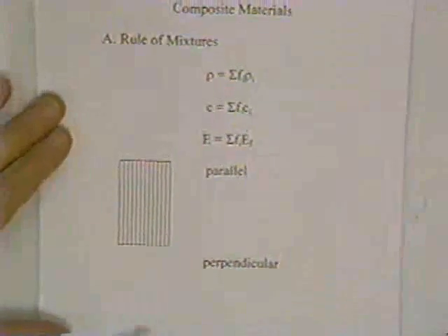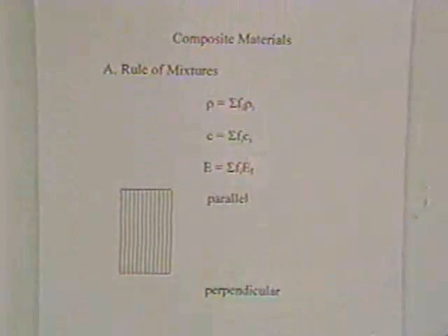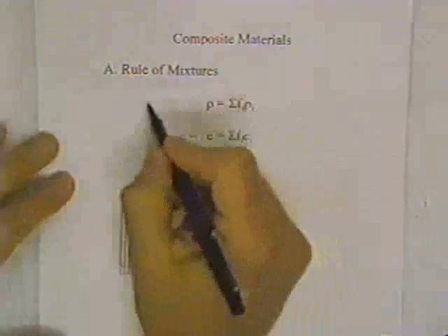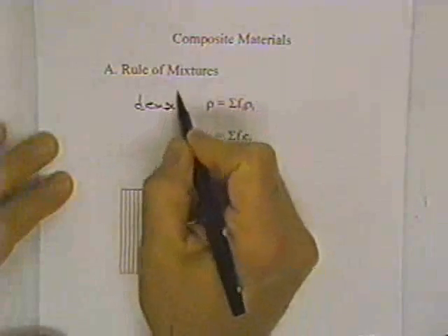The last thing that we're going to talk about will be composite materials. Some examples of the kinds of things that might be helpful to you would be application of the rule of mixtures. This says if two phases or two properties are not mutually dissolvable in one another and are independent, we can describe them by a sum of the individual properties. For example, the density.